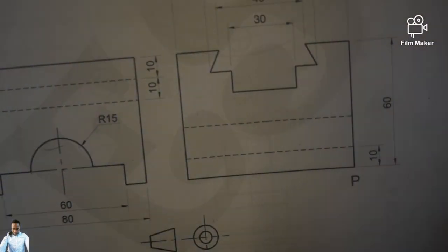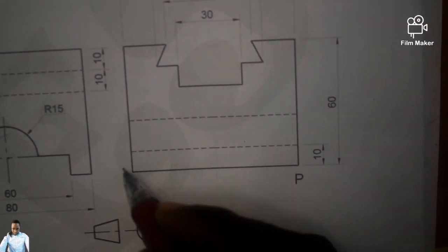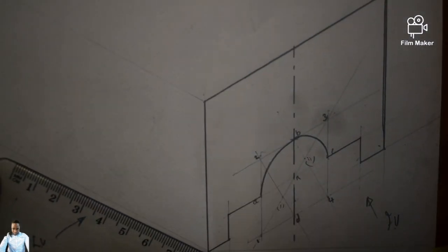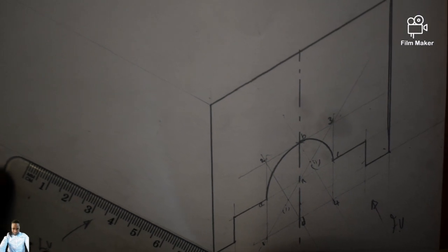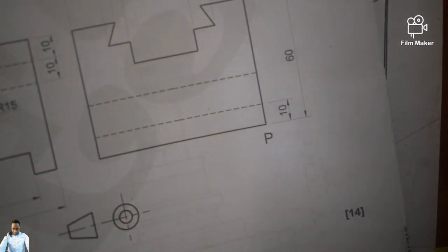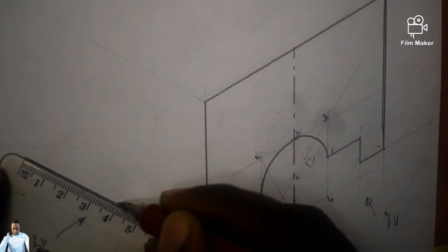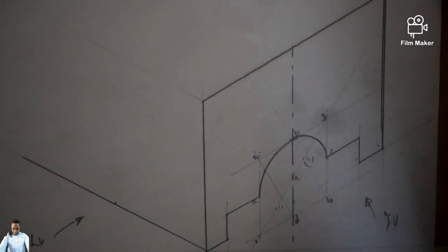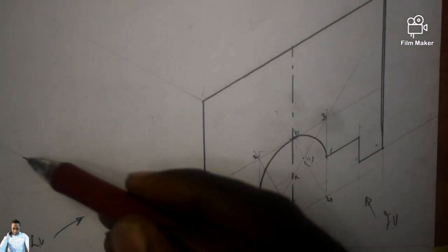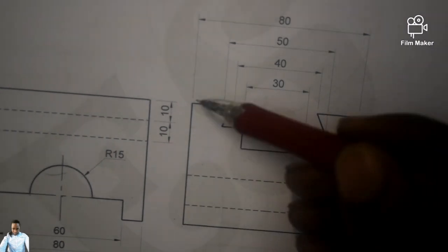You understand? So now we can come back to the left view. So we must have something of this nature this side. We must have the shape this side. So from point P coming this side to isometric is 80 millimeter. From the bottom, isn't it? There is my 80 millimeter till there. Without fail or favor, I am going to draw it dark as much as I can see it dark there by our left view. So I must get the center, which is 40. So once it gets here, I can take it vertically up. This one from there till there is which one? Is this one from here till there. So now from here going up, it's as if it's going to be this one till right there.